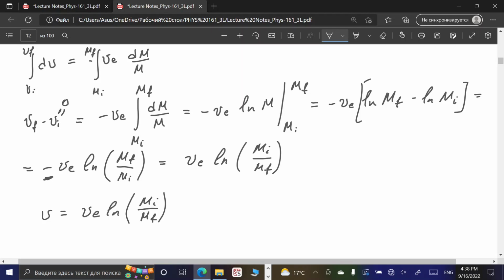So this oxidizer, which is liquid oxygen, goes through some channels in the housing of the engine as a cooling liquid before it's injected into the burning area of the engine. So that is how we dissipate external additional heat from the housing of the rocket engine by cooling it with liquid oxygen, and then use this already warmed up oxygen in burning of the fuel inside the engine. So this combination of material science and mechanical engineering in this case provide possibility to increase as much as possible the burning gases temperature and achieve very high exhaust velocity.